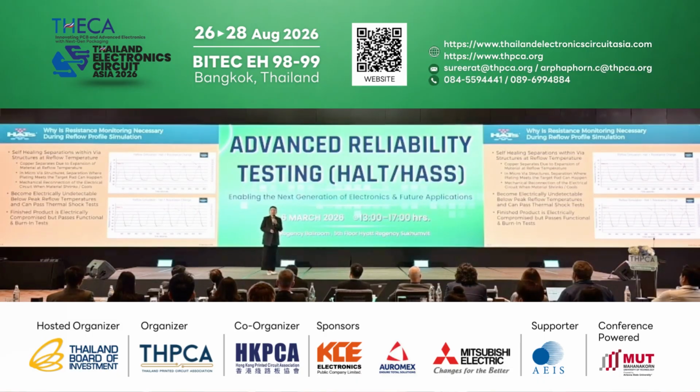And sometimes it will not be detected at all, even after the thermocycling test afterwards. These kinds of tricky or sneaky failures only happen a few seconds at the peak high temperature of the reflow.